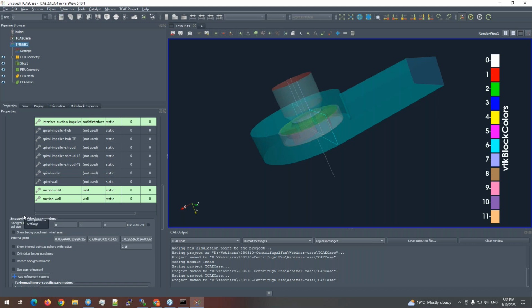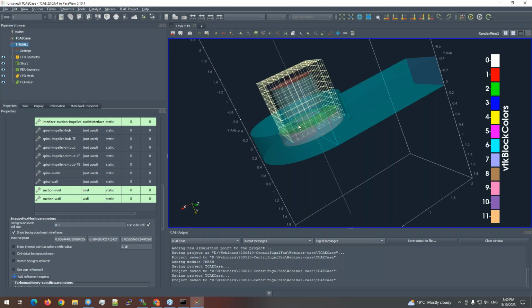And let's start with setting up the mesh refinement. So SnappyHexMesh works in a way that you first create the so-called background mesh cell size, so a hexahedral background mesh, which includes all the STLs, the whole component, and then you define the size. So I will define each cell size. You can understand it as the largest cell in the mesh, as cubes. And let's start. Okay, so I will set 10 centimeters.